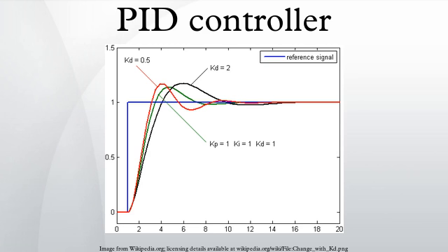The basic PID algorithm presents some challenges in control applications that have been addressed by minor modifications to the PID form. Integral wind-up. One common problem resulting from the ideal PID implementations is integral wind-up. Following a large change in set point, the integral term can accumulate an error larger than the maximal value for the regulation variable, thus the system overshoots and continues to increase until this accumulated error is unwound.